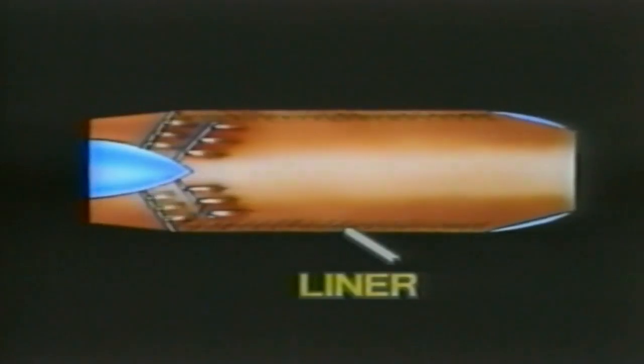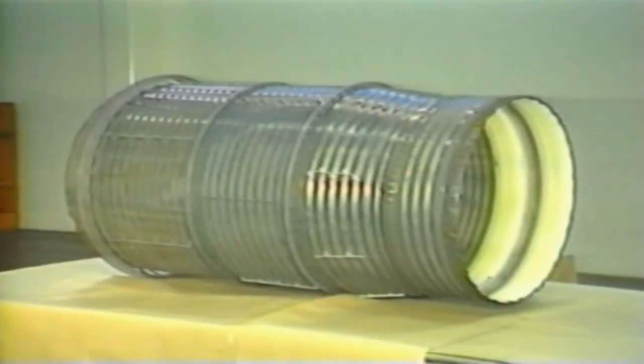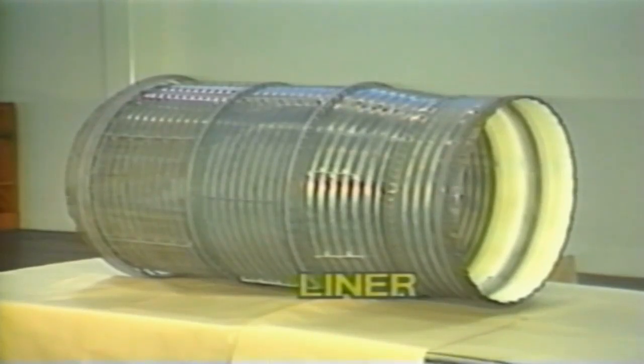The liner has a rough and tumble job to do. In fact, it serves a dual purpose. A portion of the exhaust gases, cooled considerably by the time they leave the turbine, flows between the duct and liner and then passes through thousands of tiny holes in the liner and then into the combustion area. This confines burning to the center and helps keep the AB duct cool enough to survive the extremely high temperatures.